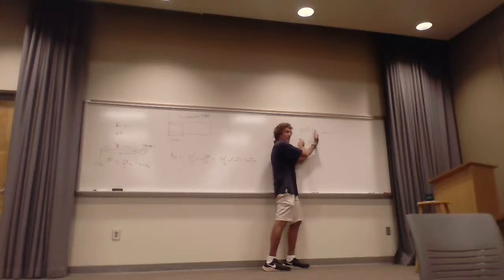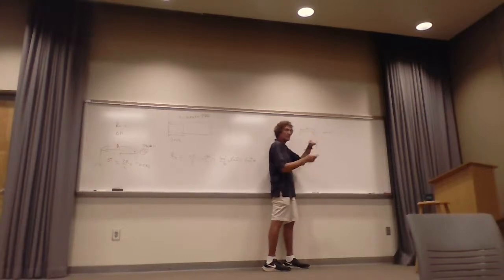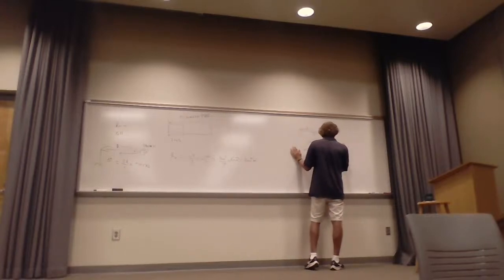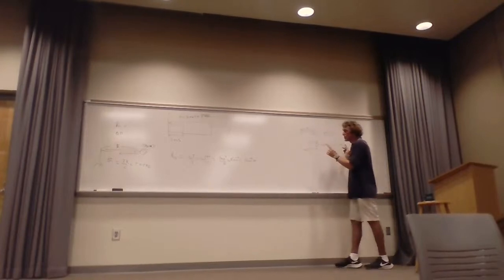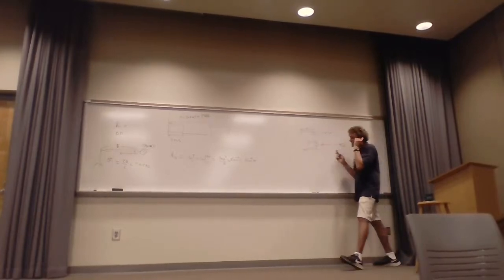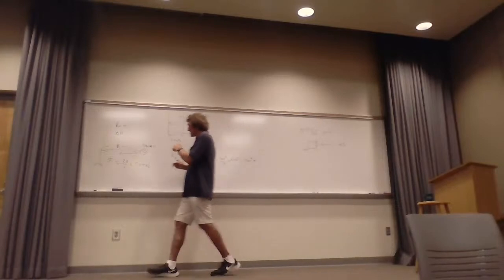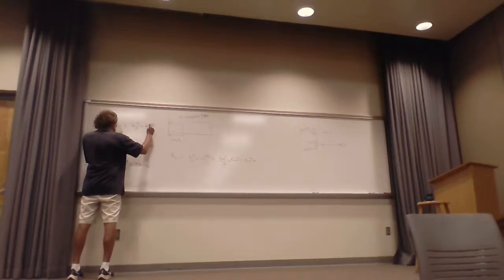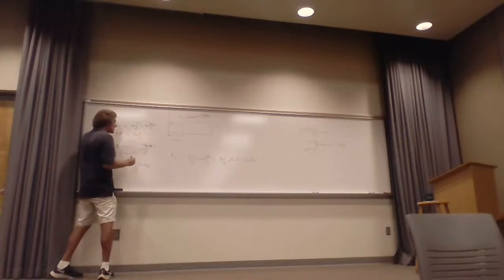Well, the thing about it is, the range resolution will be that tau, if you think about it. What does the spacing have to be between this and the next target so the two don't overlap? And if you take a look at this delta R, this is C times T over 2, or C times PRI over 2. This will be similar, C tau over 2.